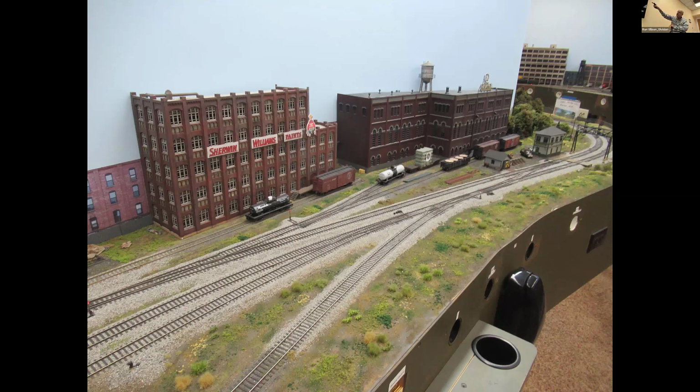So we've got a tank car here, a tank car there. Is it incoming product? What product is it? And what are they using it for in that industry? And then is it an empty tank car going to go back out? Or are they going to put waste in that tank car and ship it out? And the same with the next industry with the tank car that's there. What period of time are we in? Is it DOT 103? Are we in DOT 111? And those kinds of things. So there's a lot to think about in this kind of situation related to tank cars at a factory.